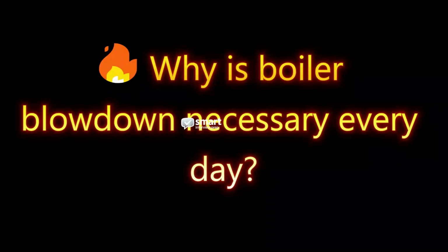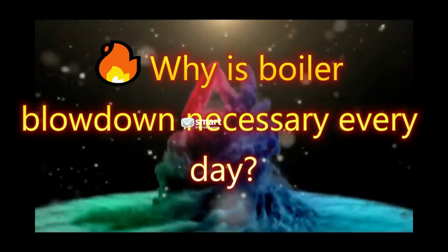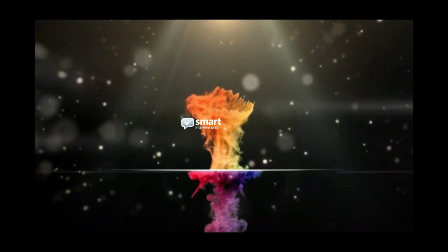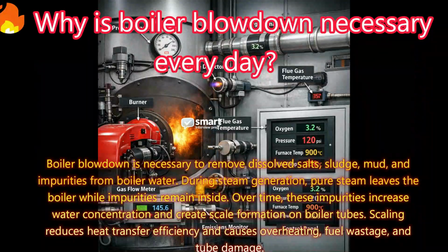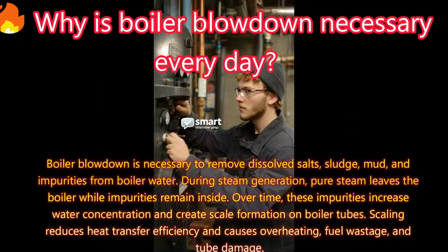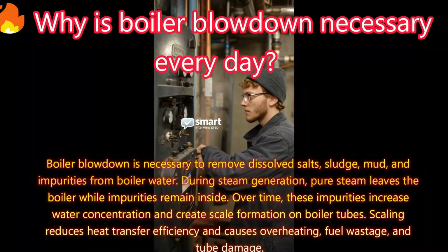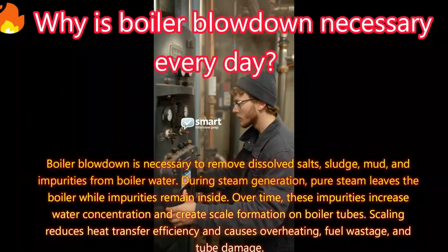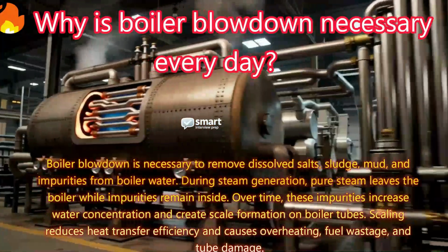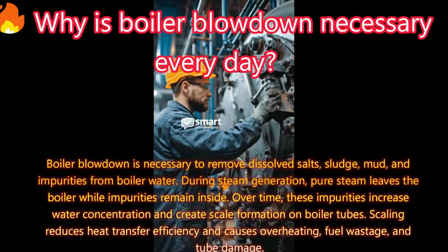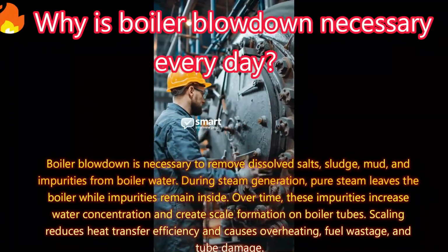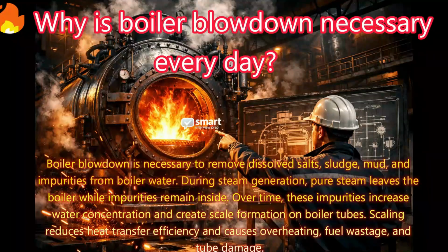Why is boiler blowdown necessary every day? Answer: boiler blowdown is necessary to remove dissolved salts, sludge, mud, and impurities from boiler water. During steam generation, pure steam leaves the boiler while impurities remain inside. Over time, these impurities increase water concentration and create scale formation on boiler tubes.